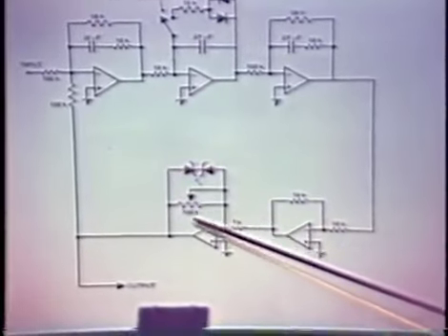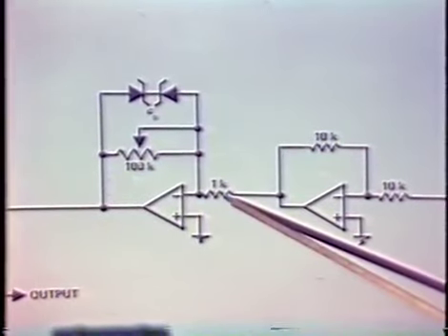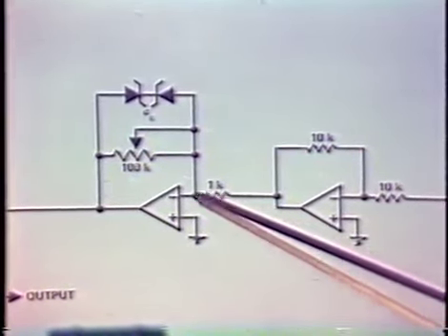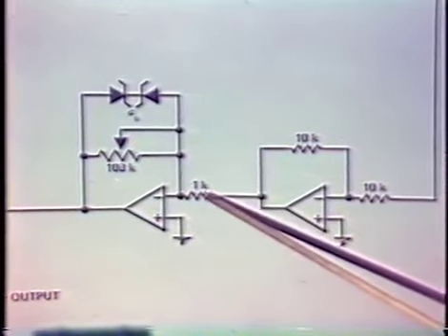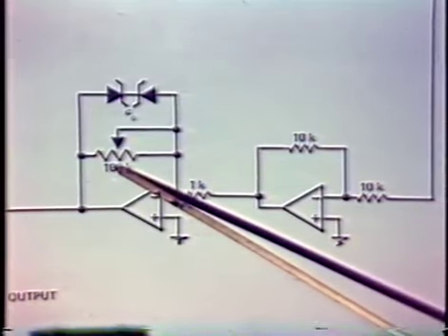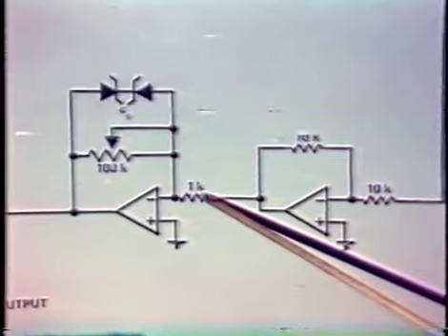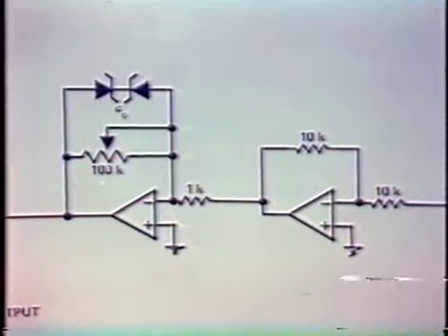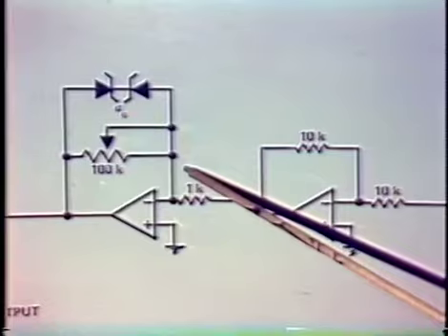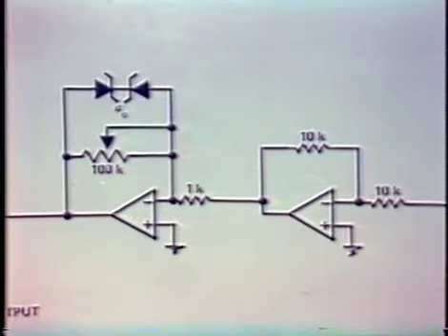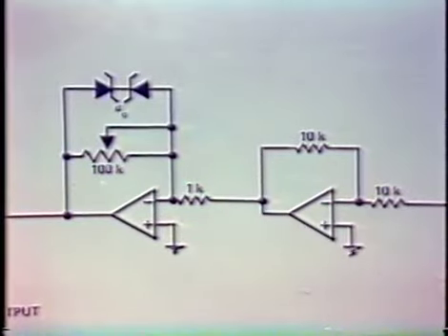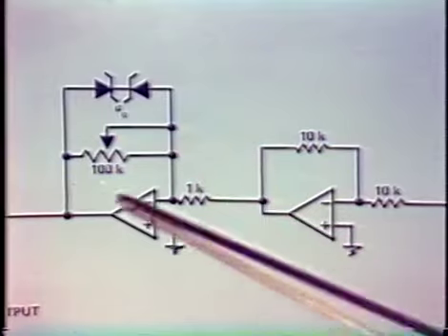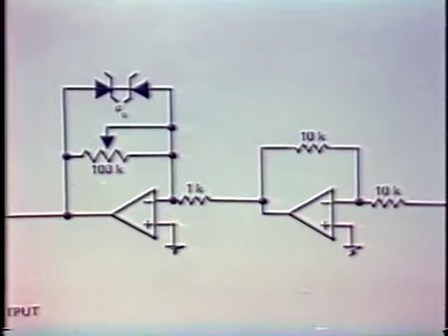We have a limiter, and we make the limiter in a very simple way. We have the usual inverting connection operational amplifier with a 1K input resistor and a potentiometer for the feedback element. The gain of this configuration is simply the negative of the feedback resistor divided by the input resistor. So by adjusting the potentiometer, we can change the gain from basically 0 to minus 100. Actually, in the actual test setup, we have a little series resistor included with the potentiometer so that we can't make the gain of this block really 0. We can bring it down to about unity.